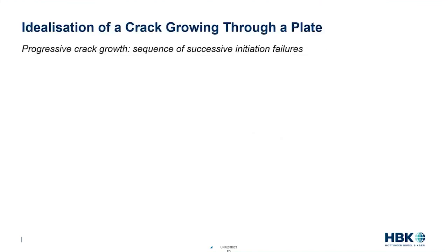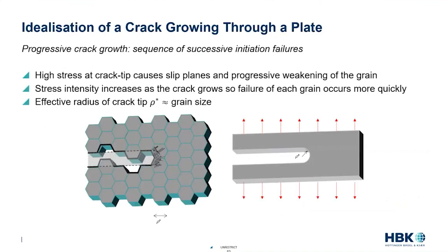The crack growth approach itself is rather unique. Dr. Glinka's thought on crack growth is that it is actually just successive failures due to crack initiation. And so each grain that the crack comes up and hits is now going to be loaded and eventually will initiate a crack, which basically causes that grain to be structurally unsound. With the concept that we have basically lost the structural integrity of a grain at the tip of the crack, his assumption is the crack isn't a sharp point. It is actually a blunt notch with the radius of the diameter of the grain.